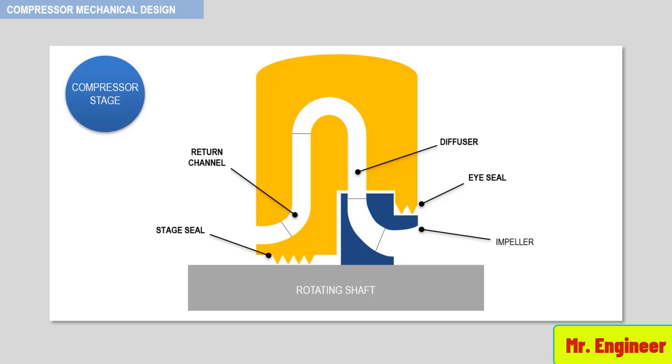Modern vaned diffuser designs, like the low solidity diffuser, LSD, move the vane up the diffuser out of the immediate effect of the impeller vanes, as depicted here, therefore eliminating significant pressure fluctuation.